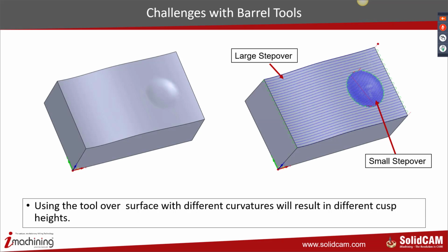The other challenge that we have with the barrel, now these are the challenges. This is not the implementation of the barrel end mill, but coming from the software side. Process certain profiles on these nice looking surfaces on which you like to machine the barrel surface. So here the scallop calculation becomes difficult because you have a big surface and then some very arbitrary shape inside there. You cannot go with the same bigger scallop. You need to have much finer scallop. Now we are working on this, and we should be able to address this challenge.